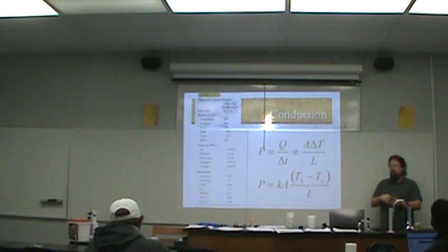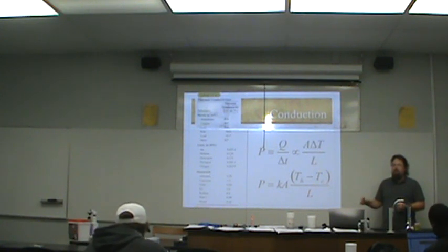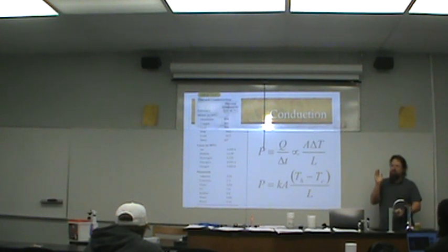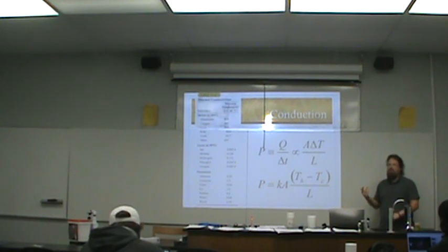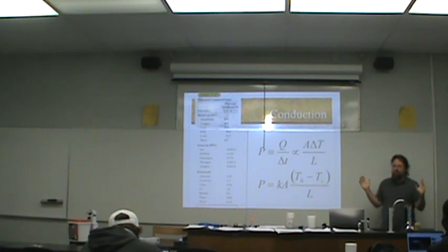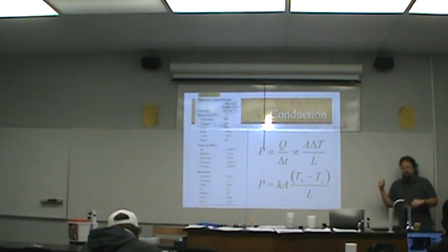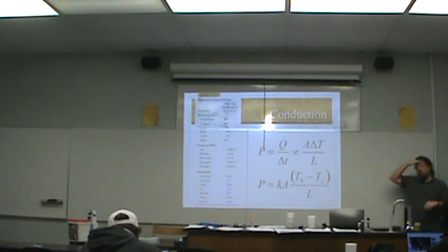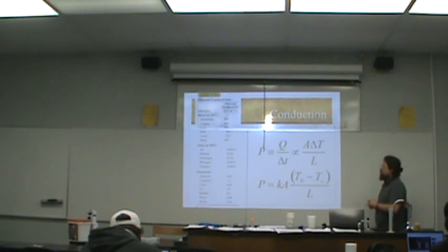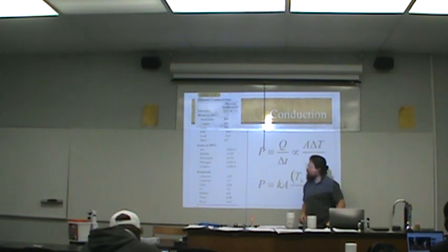An additional example with air specifically is double pane windows. Have you ever noticed that most windows tend to be two pieces of glass with a little gap in between them? That gap is full of air, which serves to insulate the window, to keep the temperature inside and the temperature outside separate. No thermal energy should cross through. The reason we would use air for that instead of any other kind of insulation is you can see through air. If you stuffed it with fiberglass, then it wouldn't be a very good window. So, these are good insulators. Thermal energy does not transfer through them quickly.